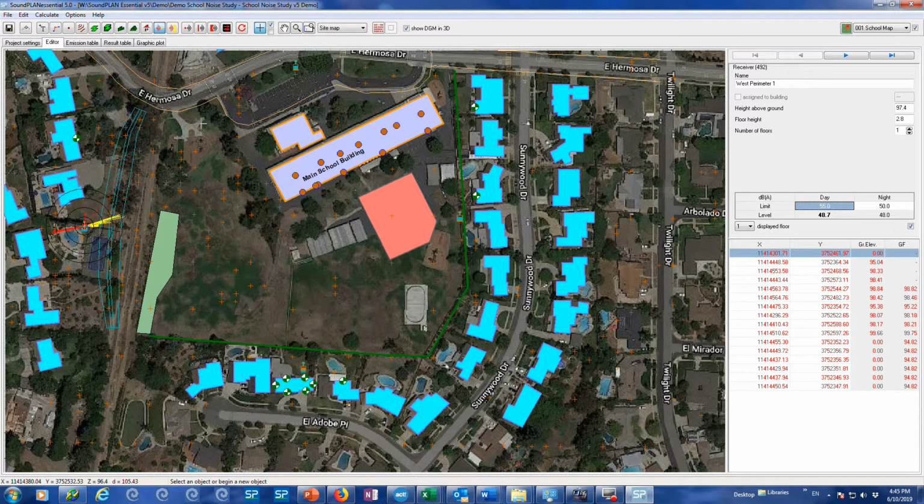If you have any walls in the project and the wall is calculated as a variant, it will automatically have the wall in a separate geo file. So the import should now be pretty flawless into the full version of SoundPLAN.